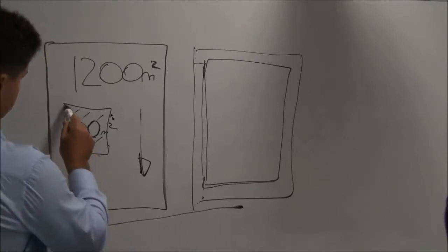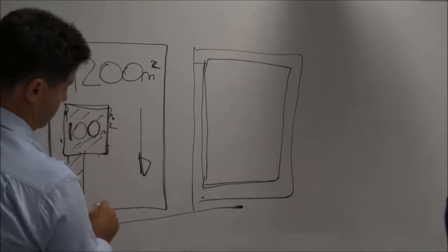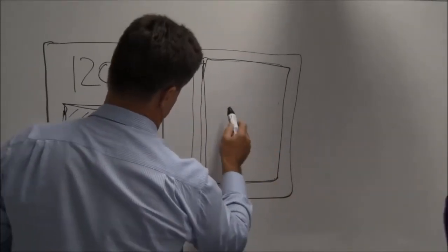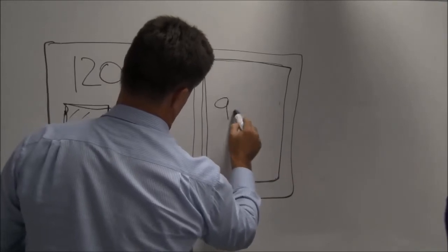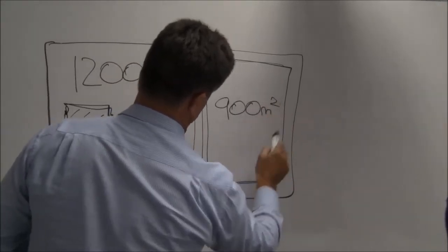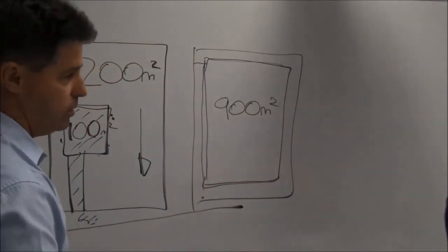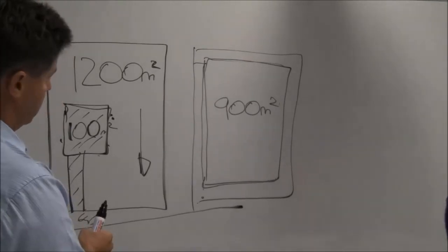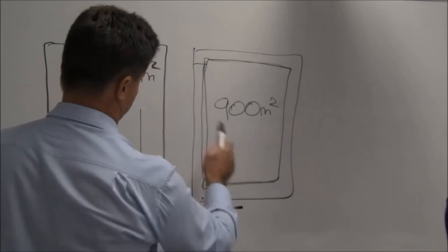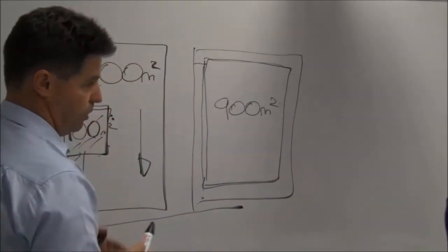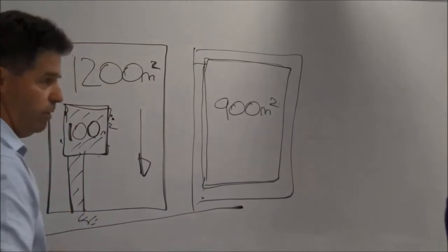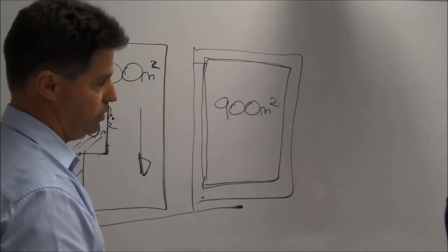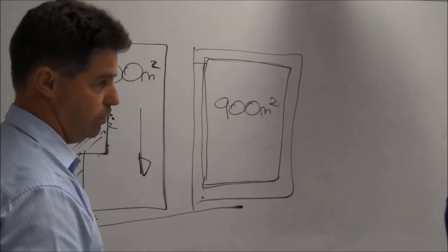So we need to then take that area that we've got, or what we had as a fraction as an impervious area, by whatever that development's going to be. So if he sets it up and he's going to do 900 square metres of hard impervious areas, and only 300 is left for landscaping and everything else, all it is is just a fraction of the total area, this total site that he's got. So 900 divided by 1200, whatever it works out, 0.85 or something, is our impervious area. Okay, so that's all it is, the fraction impervious.